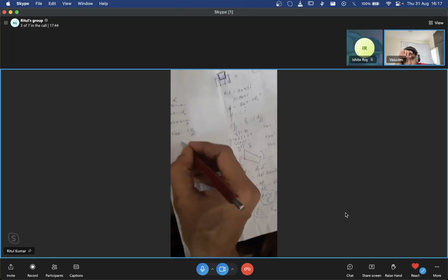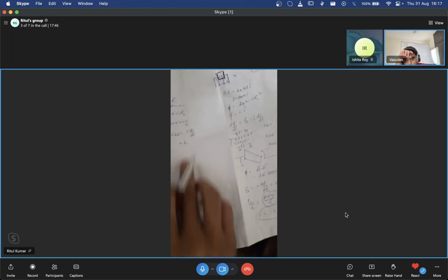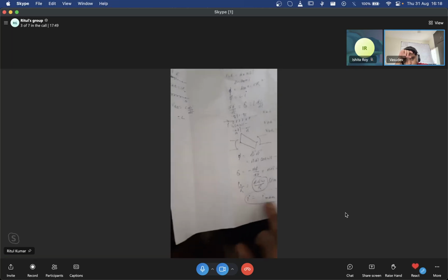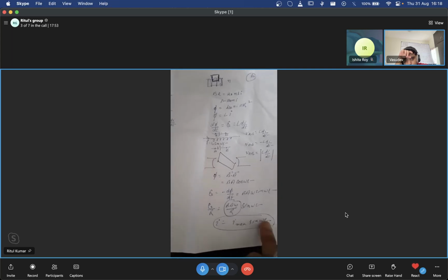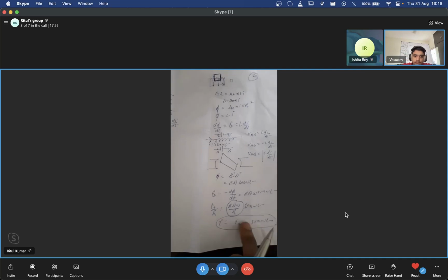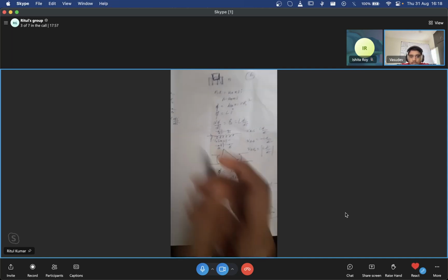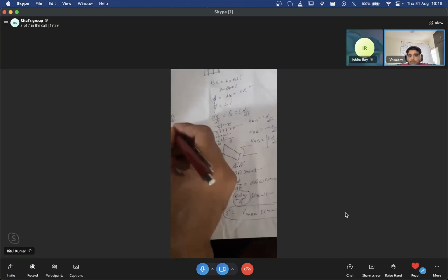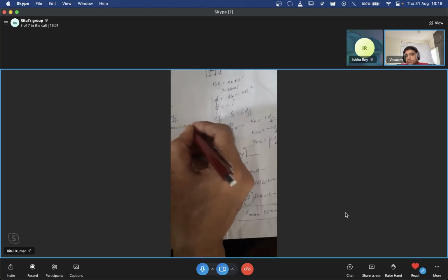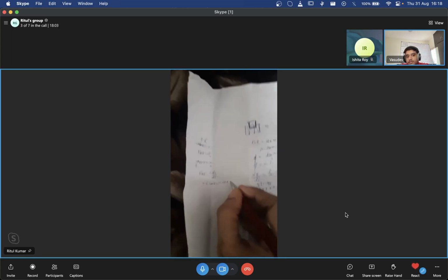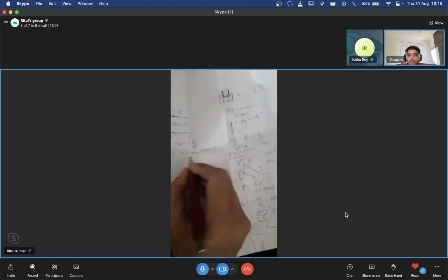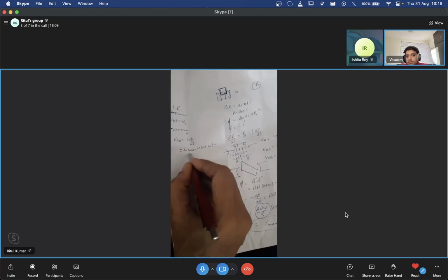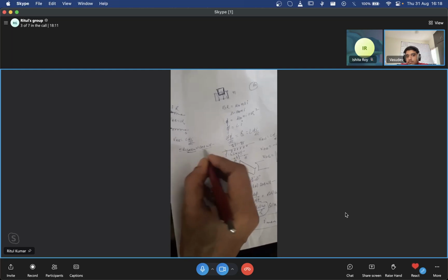Now L di by dt. What did we get from here? This is the I which I'm following. I is equal to I max sine of the angle omega t, correct? Now differentiate this, di by dt. What do we get? We get omega I max cos of the angle omega t, right? Okay. Now check this factor, please. Leave I max and cos omega t for the time being. I max and time factor.